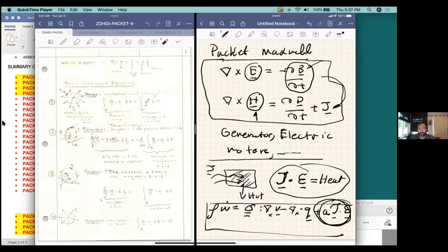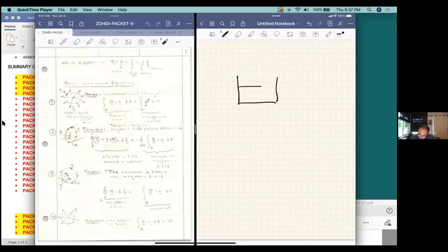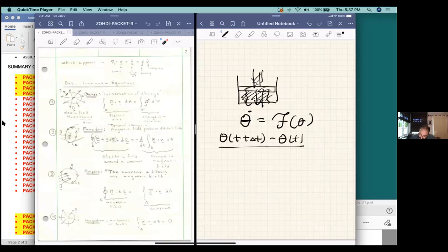So you had a pretty meaty project number 3, lots of equations, although at the end it's derived with many terms. But the equation itself is relatively straightforward to solve, because ultimately, when you take a problem like the one you had with the conduction and the plunger and the electrical current flowing through this thing, at the end, through many simplifications, you end up getting an equation for the average temperature inside that solid, which is equal to some kind of a function of theta. And of course, then you really can solve this using a standard finite difference technique. You take d theta over dt is equal to f of theta of t. And then basically the idea is theta of t plus delta t is equal to theta of t plus delta t times f of theta, and you're off to the races.